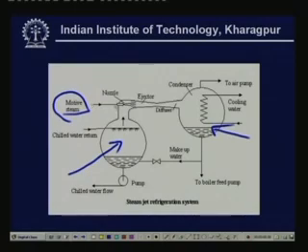When this high pressure steam flows through this nozzle, its pressure reduces and it gains kinetic energy. That means at the exit of the nozzle you have a fast moving motive steam. Because of its high velocity, it can entrain the vapor from this drum. That means whatever vapor is there in this drum gets entrained by this fast moving motive steam, right. So vapor is removed from this drum. Once the vapor is removed, more vapor is formed by evaporation of the remaining water. That means the water evaporates to provide the continuous vapor. As a result, the rest of the water gets cooled because evaporation is endothermic. So you have production of cold water here.